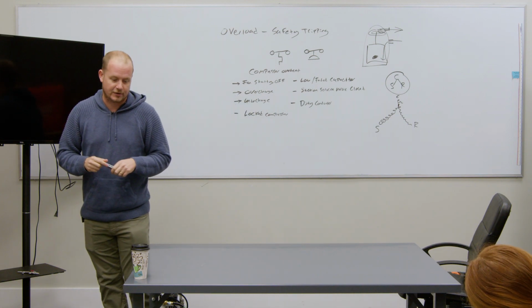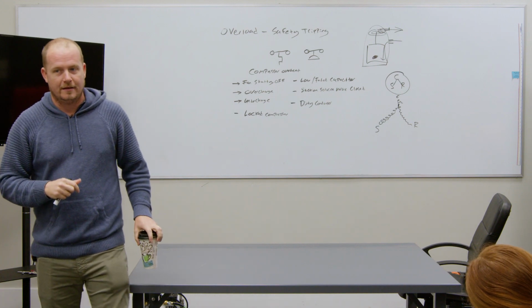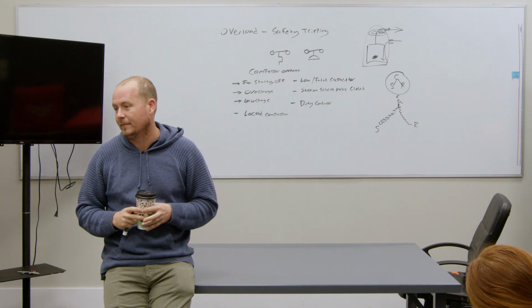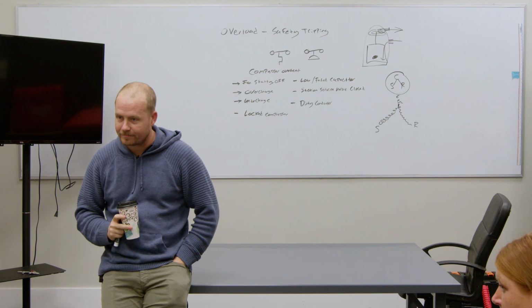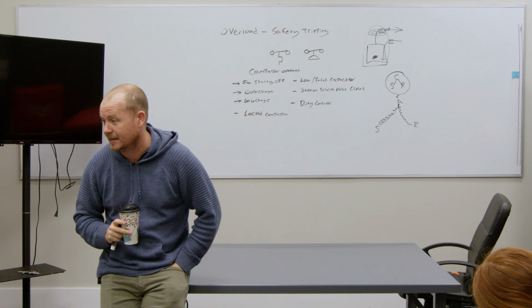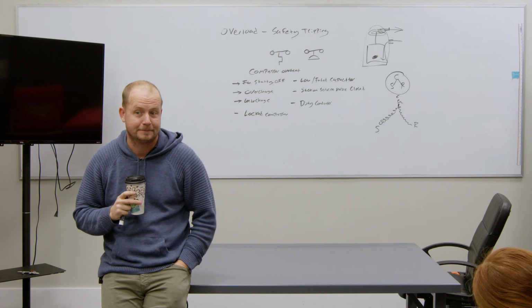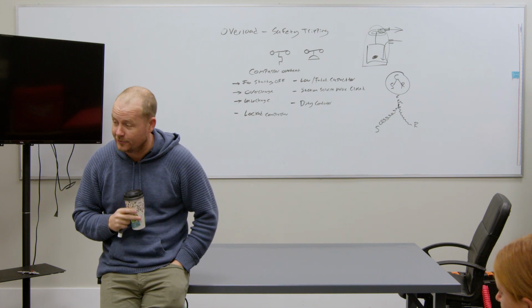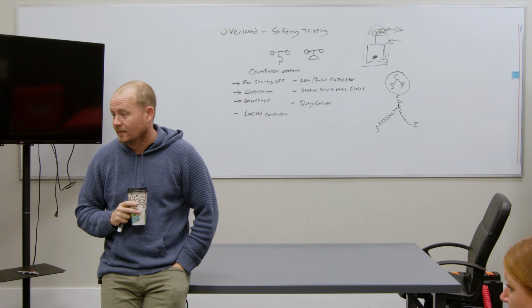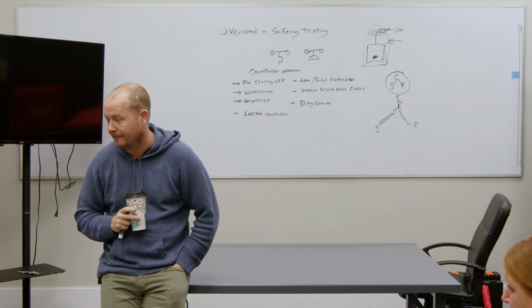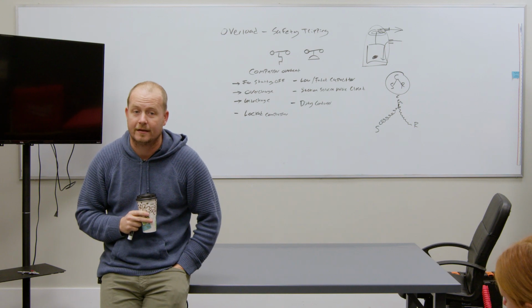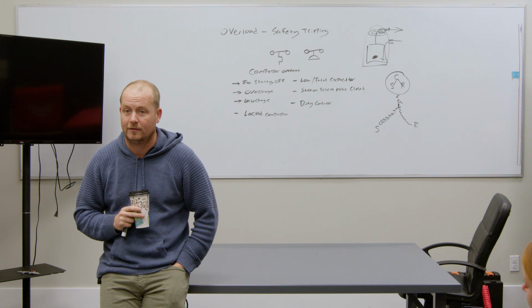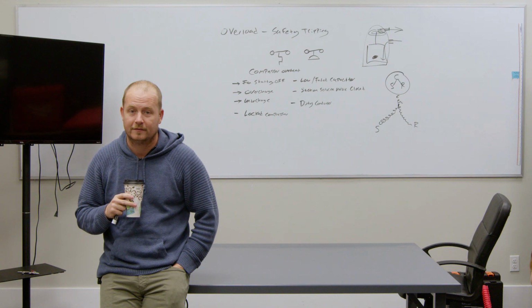Now we're going to get to Bert's controversial freezing units causing compressors to overheat baloney. Go ahead, Bert. What happens to a TXV when the coil's encased in ice? All right, coil's encased in ice, what happens to the TXV? Anybody else want to answer, or do you want me to answer? Okay, I'll answer. The TXV closes, Bert. So it's not that uncommon to find a compressor overheated because of low refrigerant mass on a frozen evaporator coil. Who else has seen a compressor overheated with a frozen evaporator coil? You have. Okay.